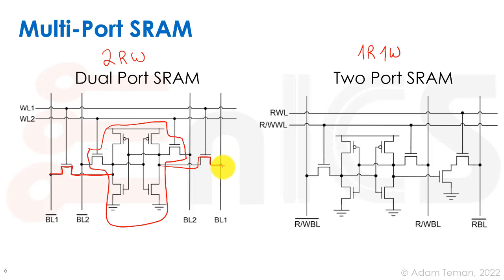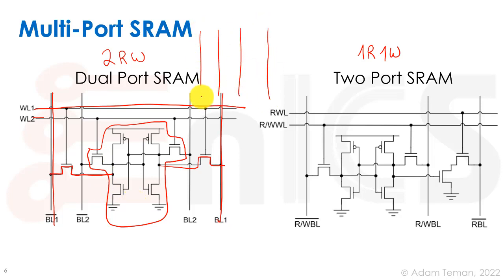Okay, and by adding another pair of access transistors and another well, another word line and another pair of bit lines, we can have one row. Remember that our array is going to be a 2-dimensional type of thing, and we can take a row over here and assert word line 1, for example, for port 1, we can turn on this row. And then through the bit line and bit line bar 1, we can read out or write to this cell itself.